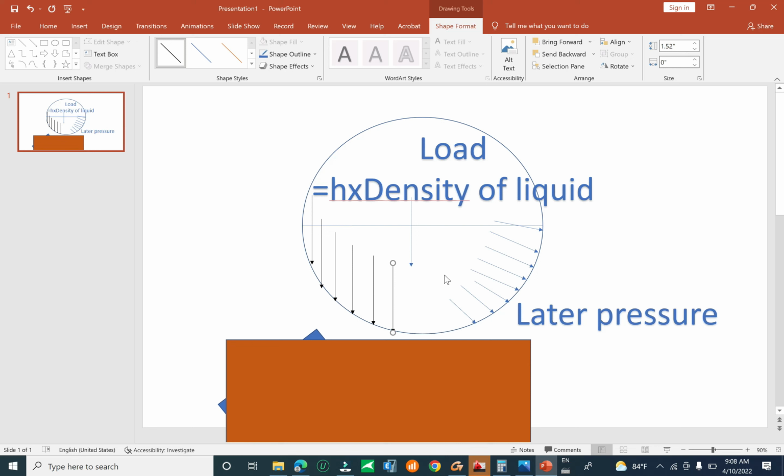So you have to correct your local axes before you can assign the load correctly. But in this case we do not change any direction of the local axes, so we have to change the load direction directly.